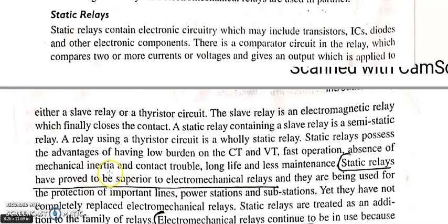There is no contact trouble. Sometimes in an electromechanical relay, even after the trip signal, contacts may not be proper. These are the advantages which overcome such problems, and also they have long life and less maintenance. That is why static relays have proved superior to electromechanical relays.